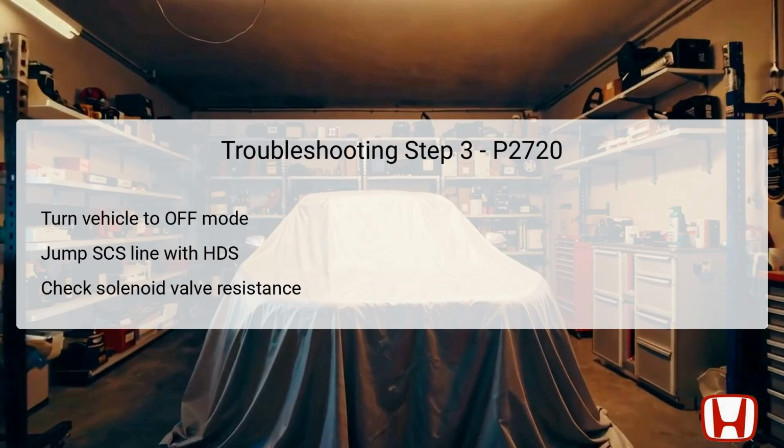If the resistance falls within this range, proceed to look for any updated service information related to DTCs, or proceed with replacing the original PCM in case a fault persists.